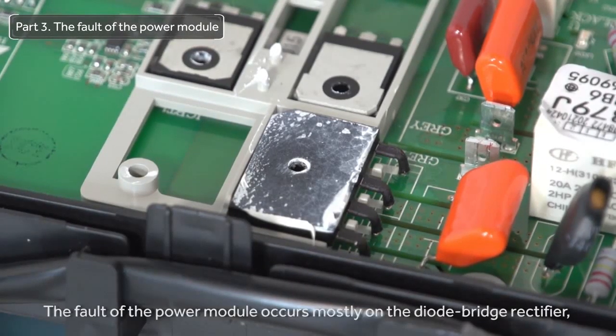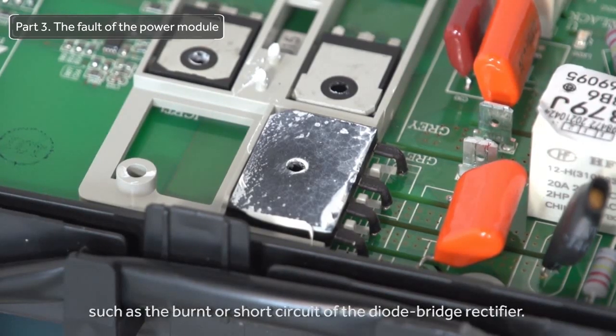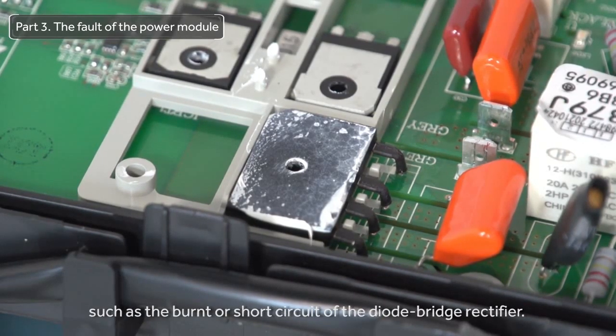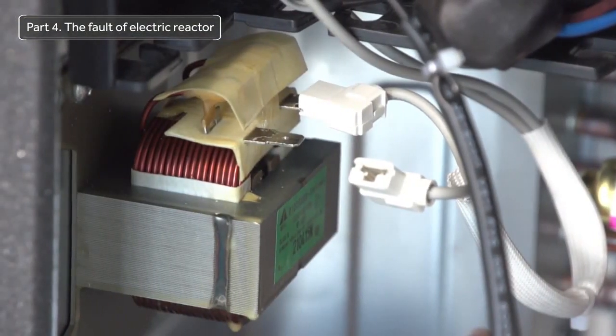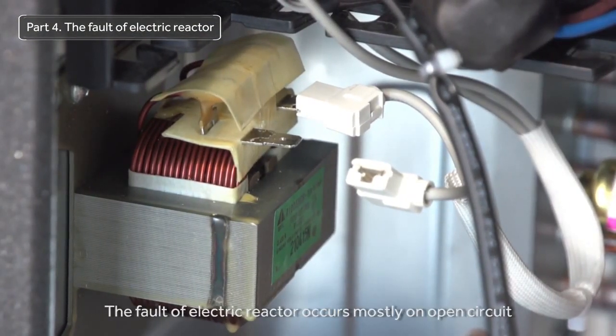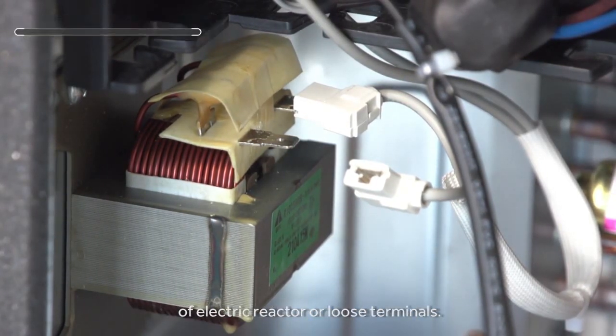The fault of the power module occurs mostly on the diode bridge rectifier, such as the burnt or short circuit of the diode bridge rectifier. Part 4. The fault of electric reactor. The fault of electric reactor occurs mostly on open circuit of electric reactor or loose terminals.